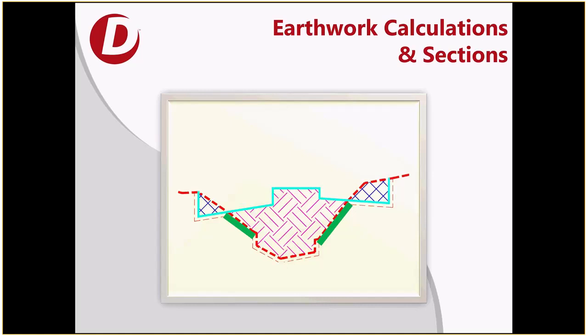We've done the adjustment for ground compaction several different ways. We can run calculations on earthwork and then manually adjust out the area times depth of ground compaction, or you can actually lower the surface in the areas where you anticipate ground compaction by the depth. And usually it's at maybe 5/100ths of a foot, 1/10 of a foot, at the most 15/100ths of a foot for ground compaction. But that's one component of what we call adjusted earthwork volumes.